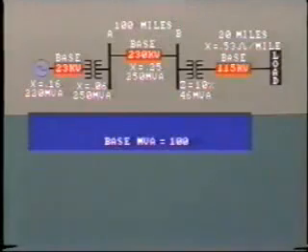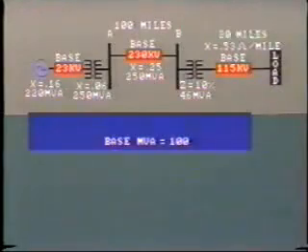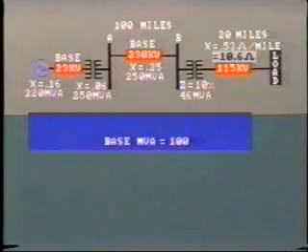Let's take our 115 kV transmission line, which has an inductive reactance of 0.53 ohms per mile. We know the line is 20 miles long, giving a total reactance of 10.6 ohms. As we have already mentioned, quite often only the reactance is taken into consideration, as line resistance is very low. Now let's convert to the per unit system.